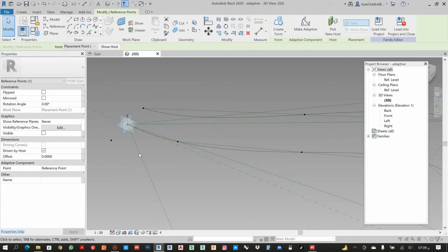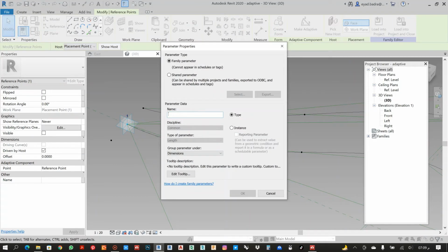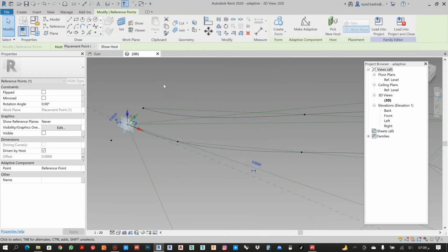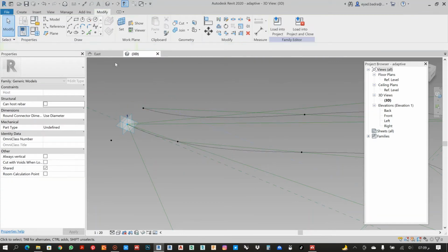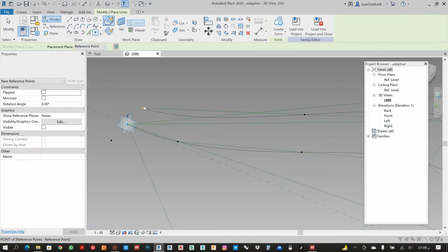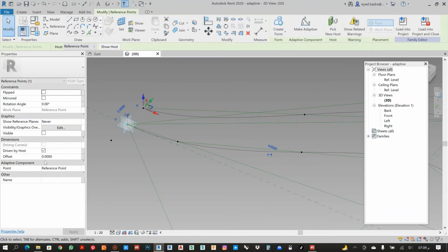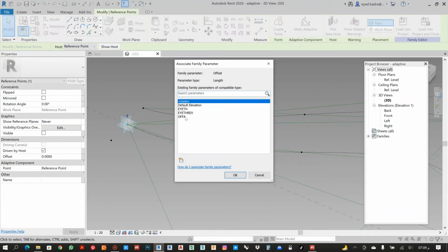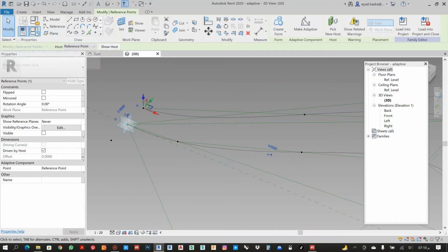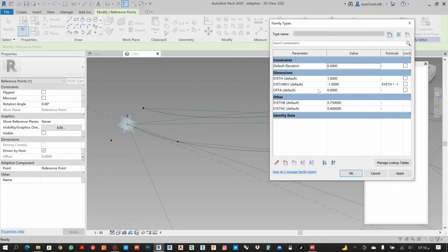It's going up, so let's say we will start to make offset A, and also here I will make another point. I will pick this plane, and it will take the same offset A. I can give also a parameter of offset A, and let's say 0.1 to see what's happening here.